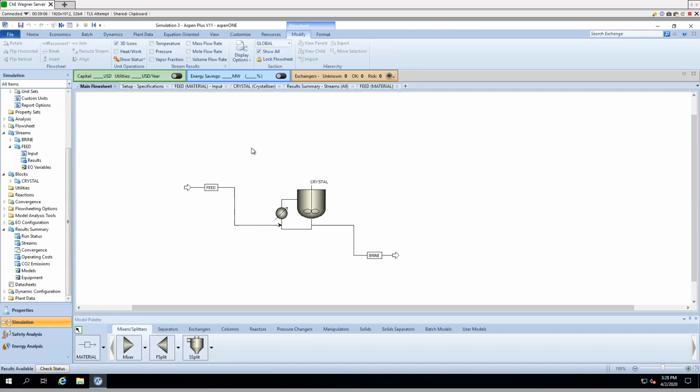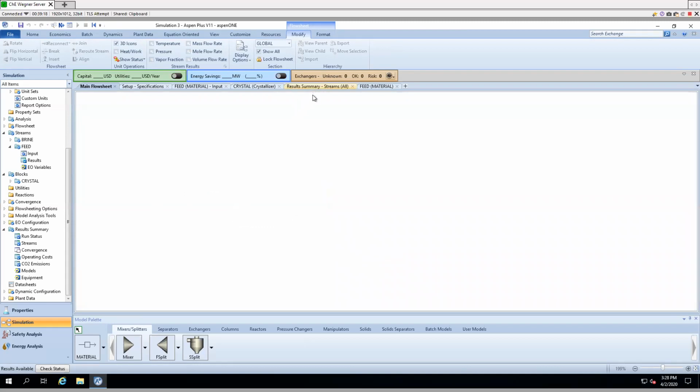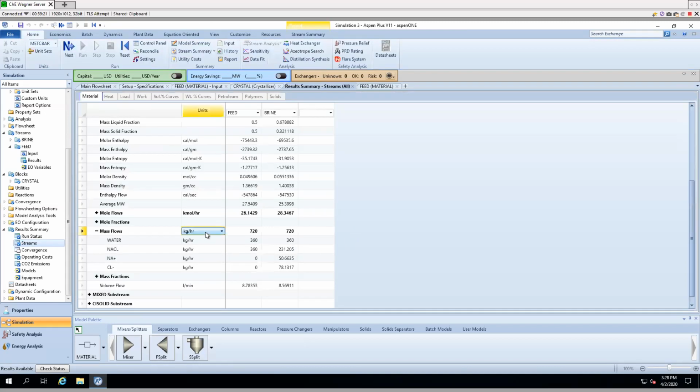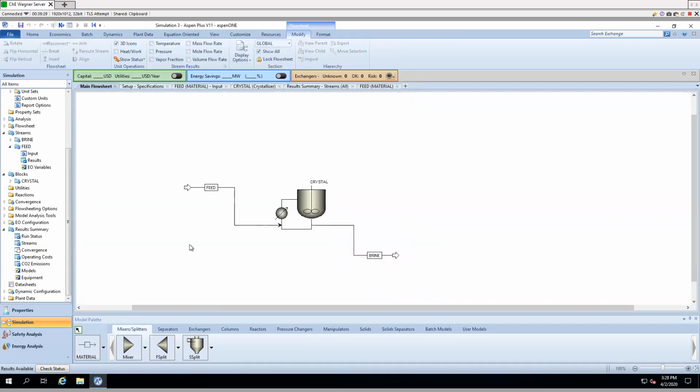Really the point of this simulation is just for us to get comfortable with feeds and solids feeds. There's not necessarily an objective we're trying to reach here. Really the biggest thing we wanted to get out of this simulation was this stream information here. Because based off of this, that's really it. And so, yeah, you could make an argument. Let's say your objective, if you were to do something in real life, was to dissolve all of the sodium chloride, right? Yeah, you're right. We would need more water because currently we have quite a bit left over. And if our goal was to dissolve it all, we're not achieving that goal.